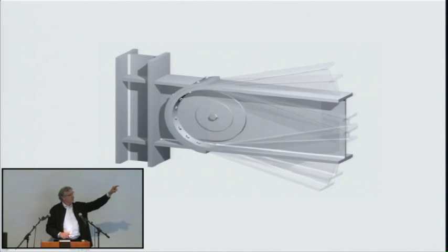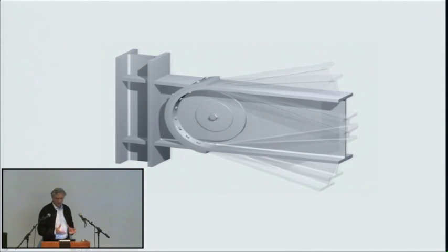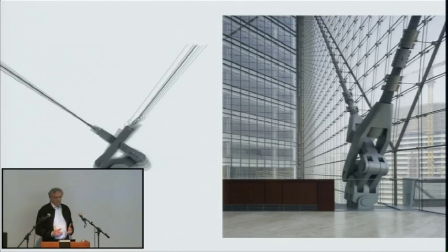But the idea of using a pin and a curved connection that's clamped together with a friction type connection, and when the load is high enough, the joint will move. Instead of deforming and yielding and failing the base material, the idea is that the energy is dissipated through this friction surface. Allowing buildings to behave naturally. The flow of force, the flow of movement, the idea that these models can be taken at a very simple level and then built into something that's very complicated.